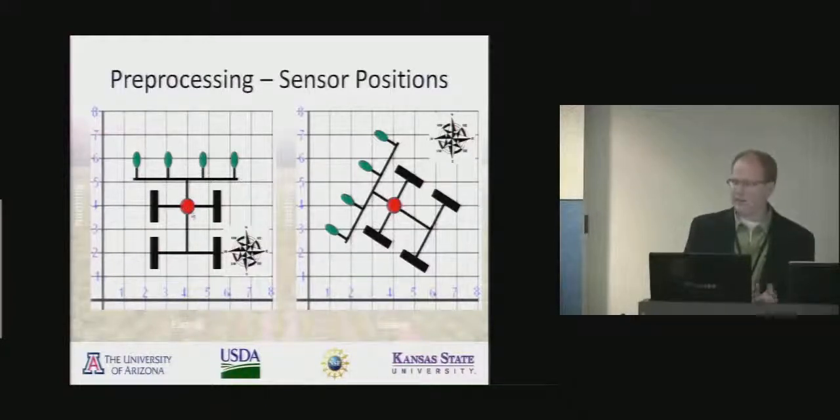And then the easting offsets from the receiver would be about 2.5 meters for this sensor, and 1 meter, say, for this sensor. That's negative because we put in easting, but this would be west. You look at the compass here, this would be west.